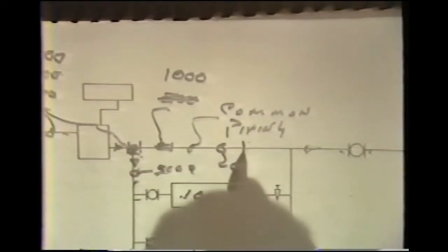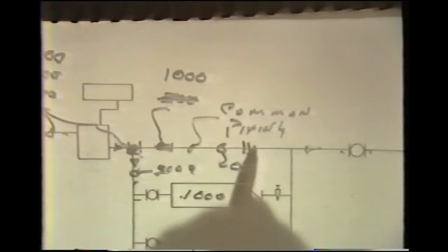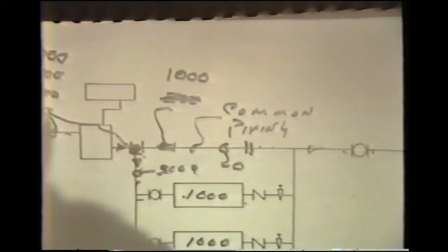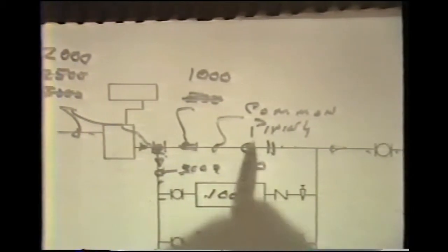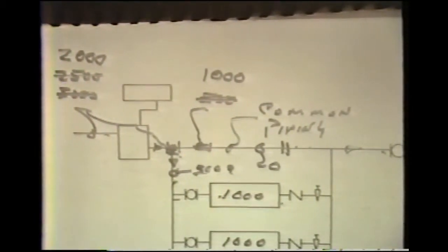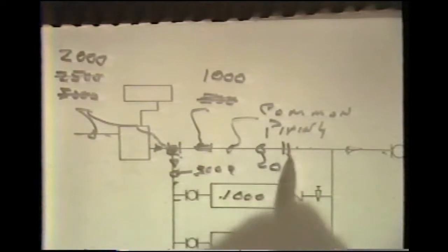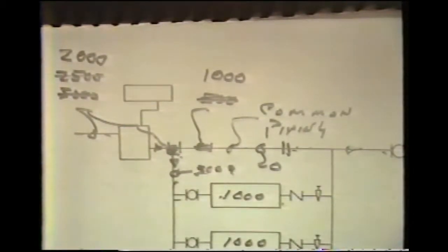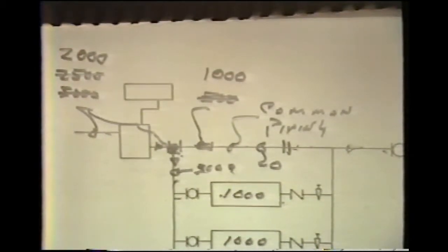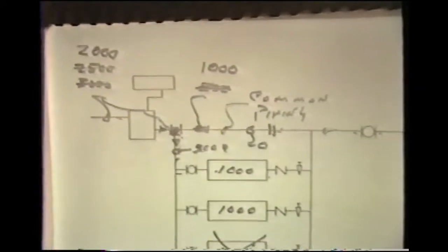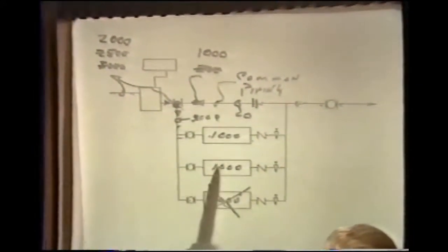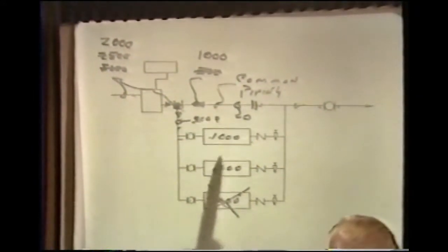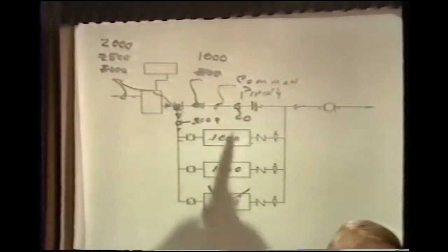Now, given that we have some method of determining flow rate in the common piping, which can be easily determined as through a turbine flow meter, we can, as soon as the flow rate reaches 1,000 gallons per minute, or flow rate associated with one of the chillers, simply take a chiller off the line, and this would return the two remaining chillers then to full load operation.